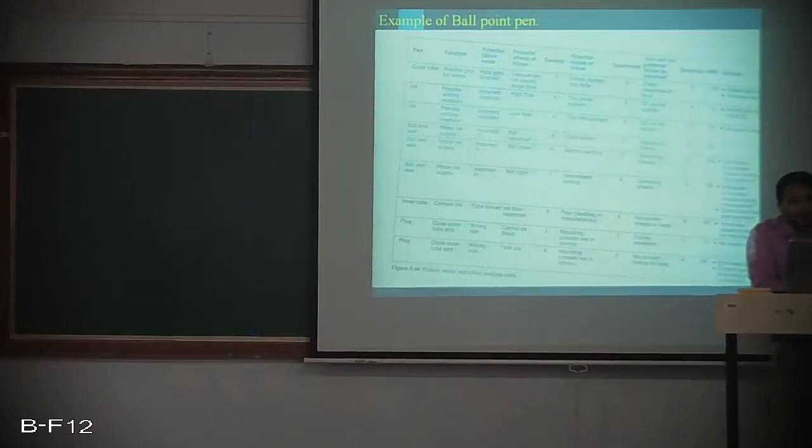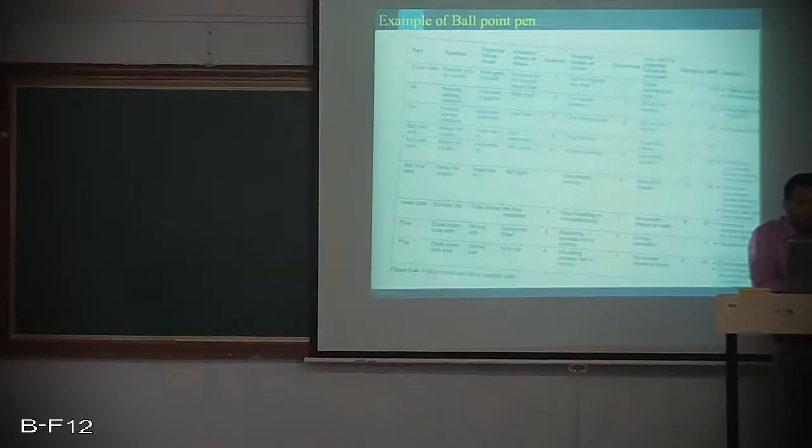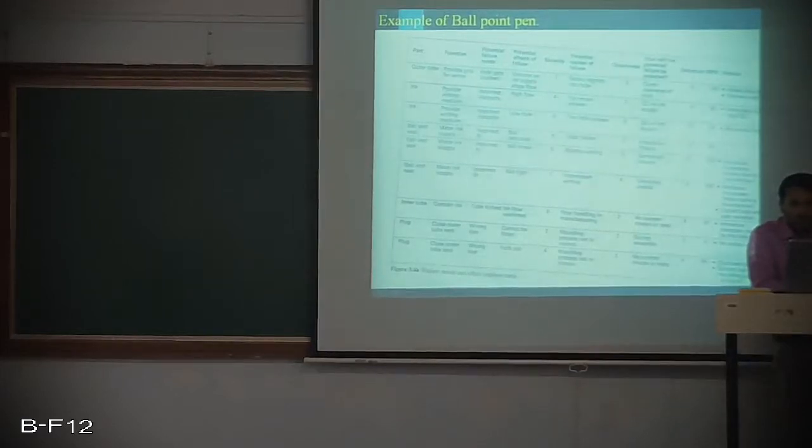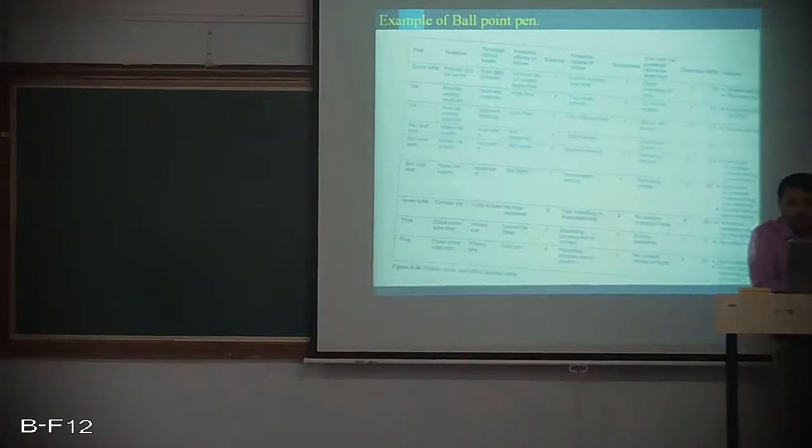Potential cause of failure is debris entering the hole. Occurrence is 3. How will the potential failure be detected? Check clearance on the hole. Detection, you can detect it very easily, it is 5. The risk priority number given is 105. The recommended action is to make a hole and remove the cap.